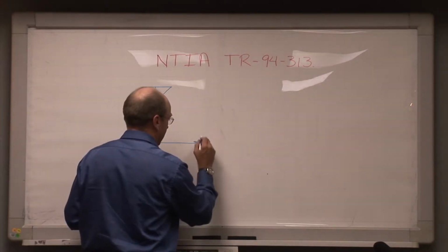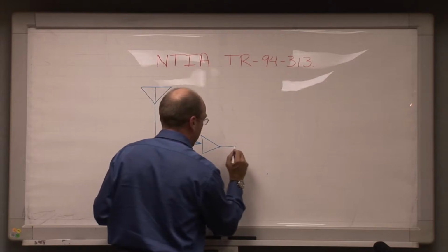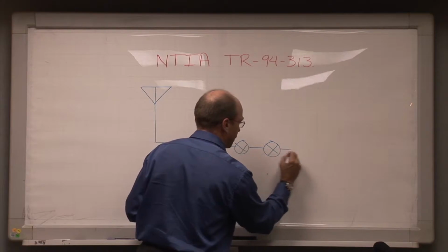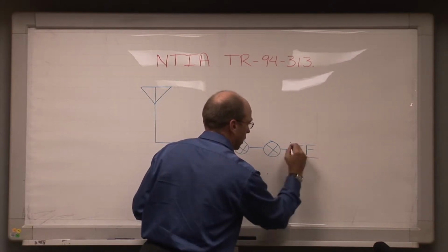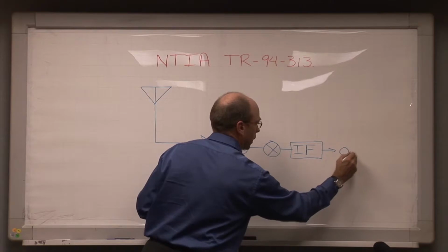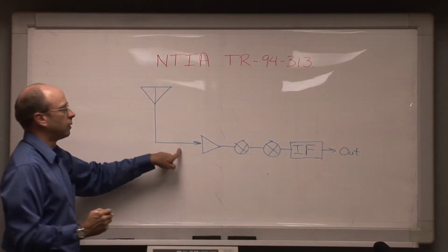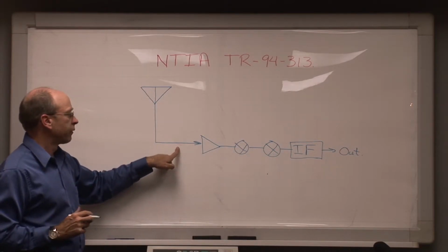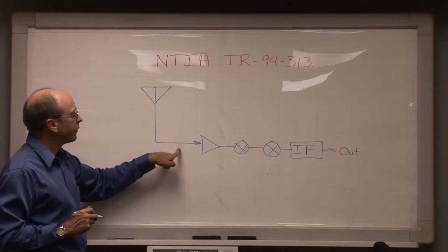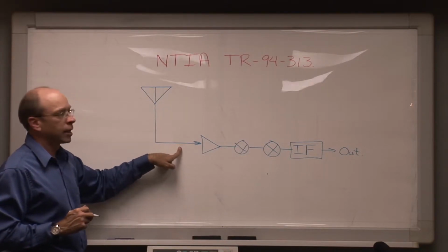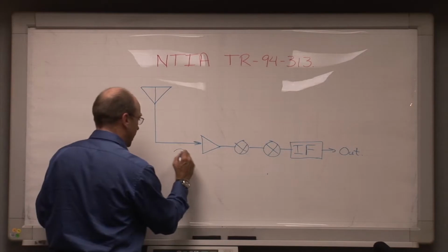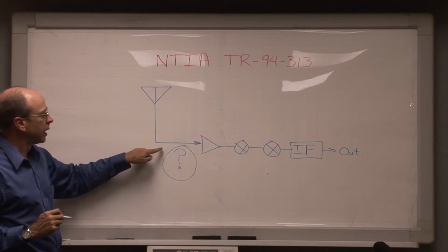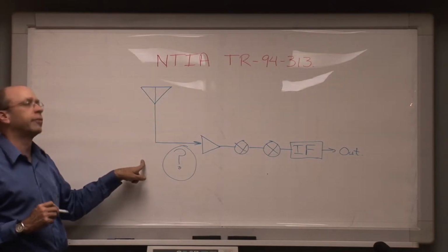And the first thing that we typically look for in a block diagram like that is in fact whether they do or do not show, back to the IF and then the output, whether they do or do not show any kind of filtering right there. It is possible that someone might have neglected to put a filter into the diagram if it exists, but if you don't see a filter there and people say that they're getting some kind of interference, you've got to immediately consider the possibility that they are in fact possibly experiencing some kind of RF front-end overload problem.